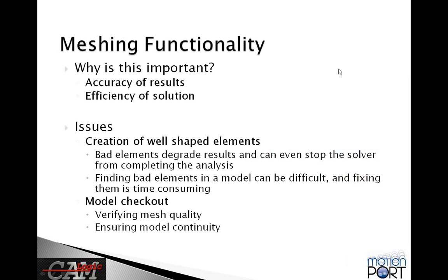Okay, so the next advanced area is this meshing and the interactive meshing. There's also issues of mesh quality. So you want the mesh to have well-shaped elements. You can check the quality of the elements, which has to do with their shape. And so then finding the bad elements can be difficult if you have a very complex element and maybe you have hundreds of thousands of elements. So the software needs to help resolve that. So there is a way to check that out, and we'll see more about that shortly.